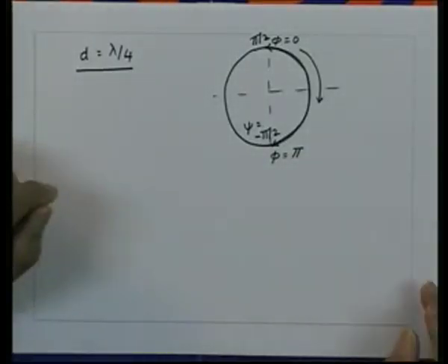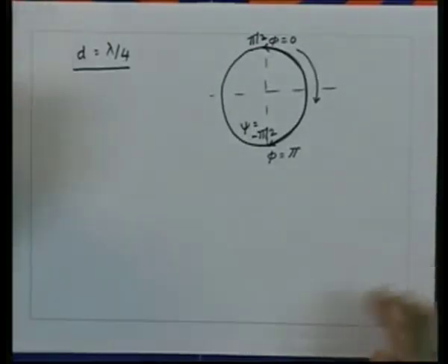So now for nulls to be visible in the radiation pattern, two things must happen. One, the root must lie on the unit circle. Second, the root must lie in the visible range of psi. Then and only then can we see the nulls in the radiation pattern. If either does not happen, it will not represent a null in the physical space.